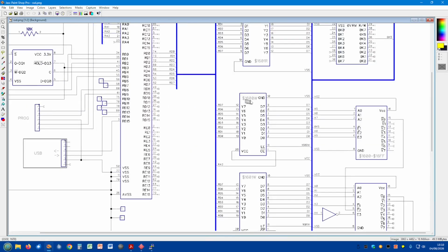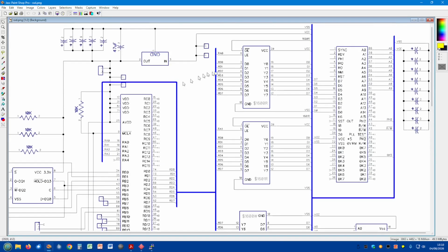We'll be working at address 1600 and 1601. 1600 being the data coming in, so that would be a whole byte, either a data byte or a command. And then this one is sort of like a control at address 1601, where certain bits mean certain things. I'll put the data on here and then turn these bits on and off, and the microcontroller will be scanning these ports. So that's how we transfer the commands. And when it replies back through these, it uses the same address. Writing goes to here, and reading comes from there, and so forth. And this will switch between them as necessary.